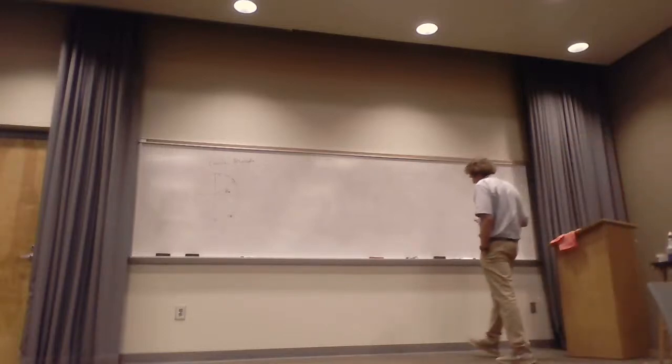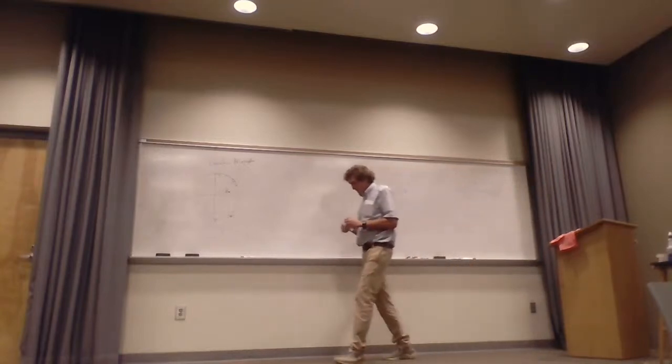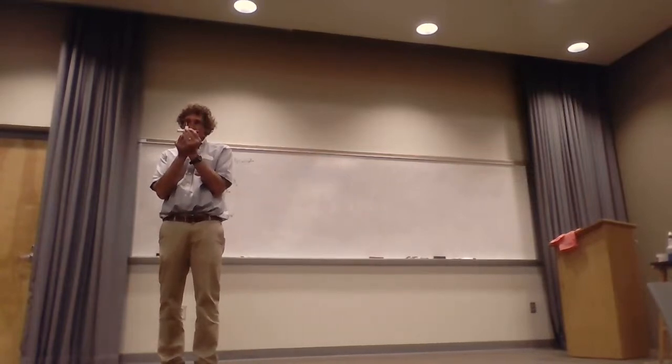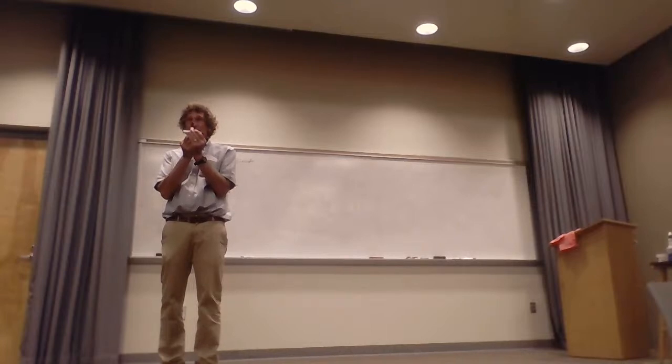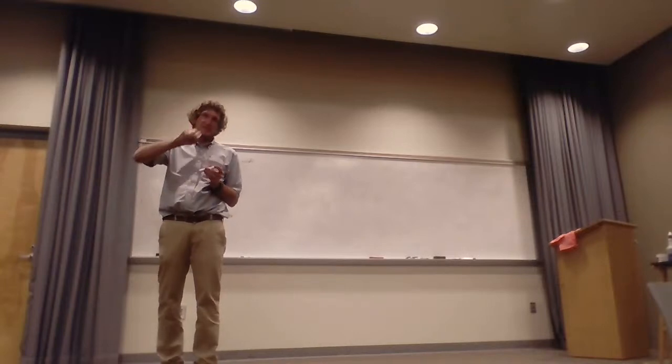So that's circular polarization. Now, if the magnitude of the currents is different, or the tangent lengths are different, or both, then you can get something that's neither circular nor linear. That's called elliptical, and you get an ellipse. Do y'all follow me on this?